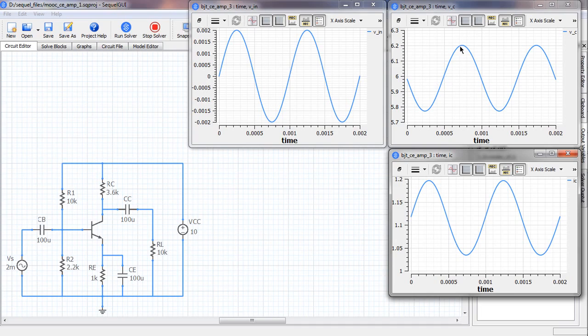And the peak to peak variation here, let's see how much that is. This one division is 0.1 volt. So we have 0.1, 0.1, 0.1, 0.1, and maybe 0.02 or something like that. So it's 0.42 or 0.43, and we expect 0.45. So it's reasonably close.